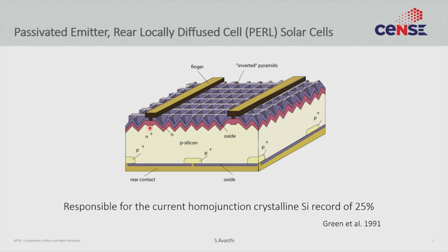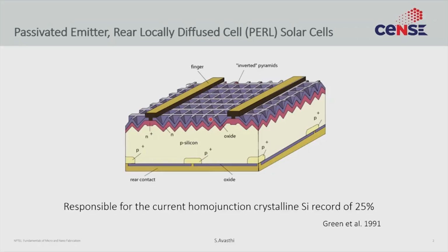The inverted pyramids are a little interesting to make. You typically would use anisotropic silicon etching. Now if you remember the wet etch lectures, you will remember that when you take the silicon 100 surface and introduce this to something like a KOH or a basic solution, you start getting these facets. And these facets are the silicon 111 facet, which typically is around 54 or 56 degrees with respect to the surface. So you can basically make these pyramids with that 56 degrees angle,